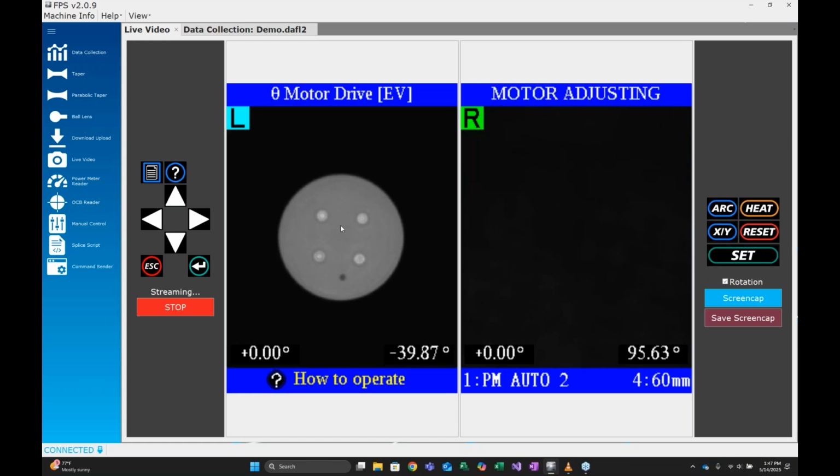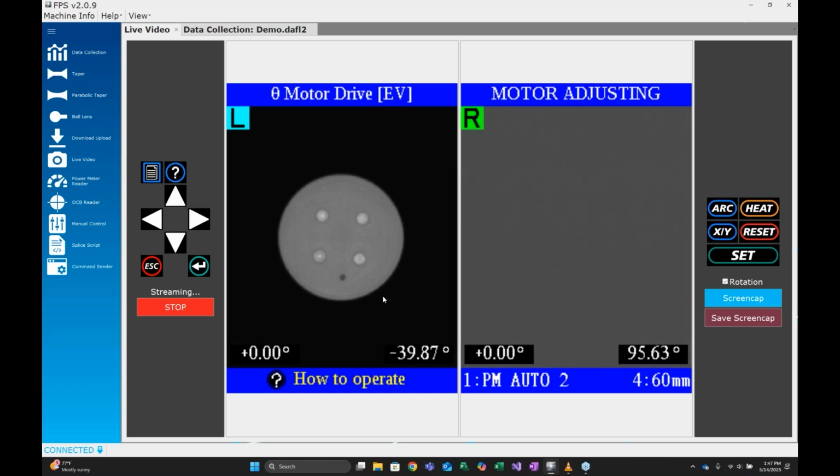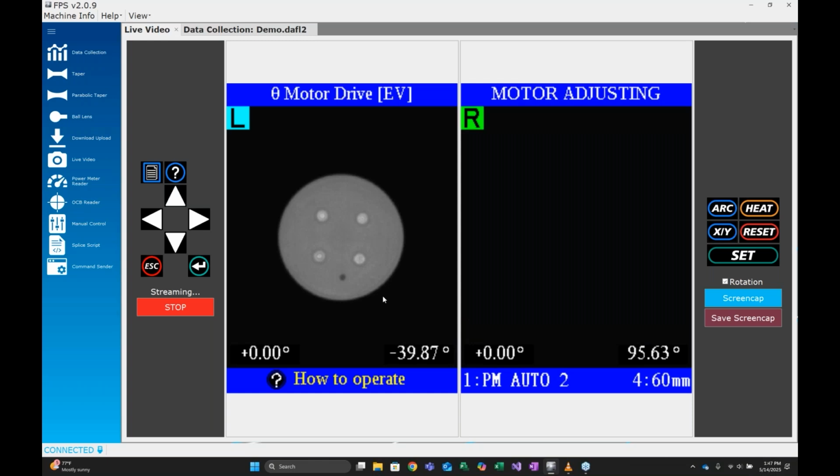All right, so this is the end view of the actual fiber that I have in here. And what you can see is it looks like these have little trenches around it, right? But in reality, what you're seeing here is some higher order modes popping up in these cores, right? Because these cores were meant for near infrared, your telecom 1310, 1550 wavelengths. However, the much shorter visible wavelength will generate a few first or second order modes in that core, right?